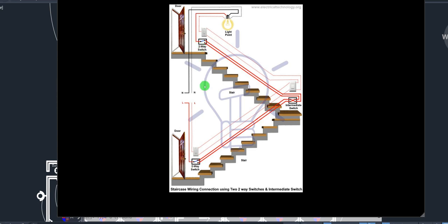All right. We also have a two gang two-way switch, meaning that it has two buttons, but you can use it for two places. We also have a three gang two-way switch. It has three buttons, but it's also two-way. You can use it to control another three gang elsewhere. All right. That is how the name implies. So the function of this, there is also another one called the intermediate switch.